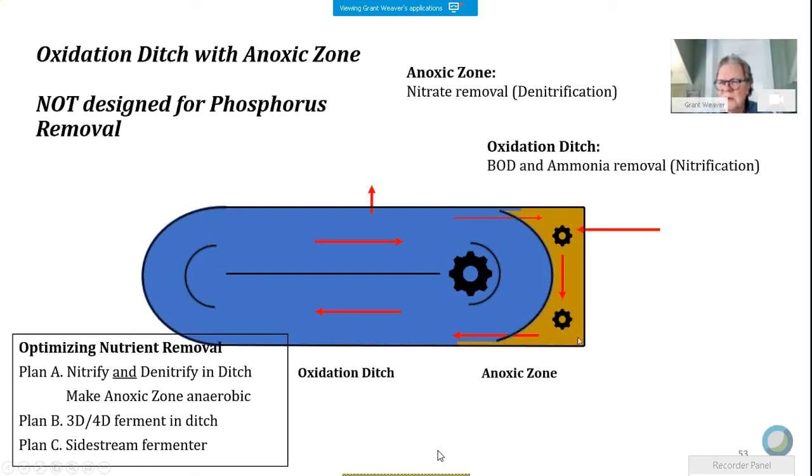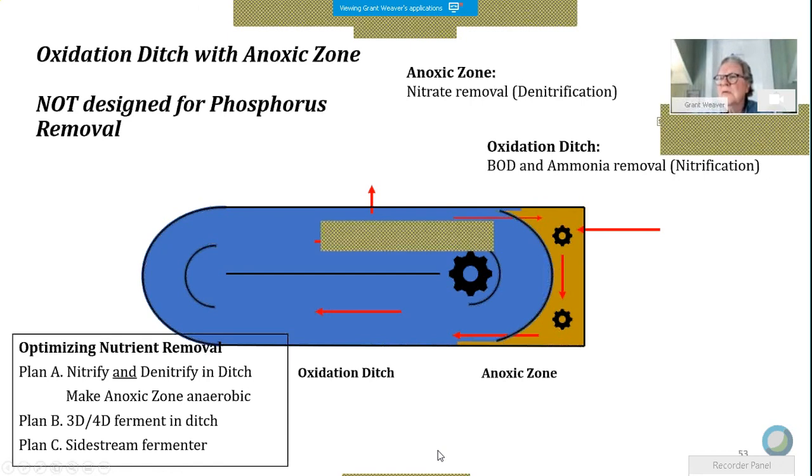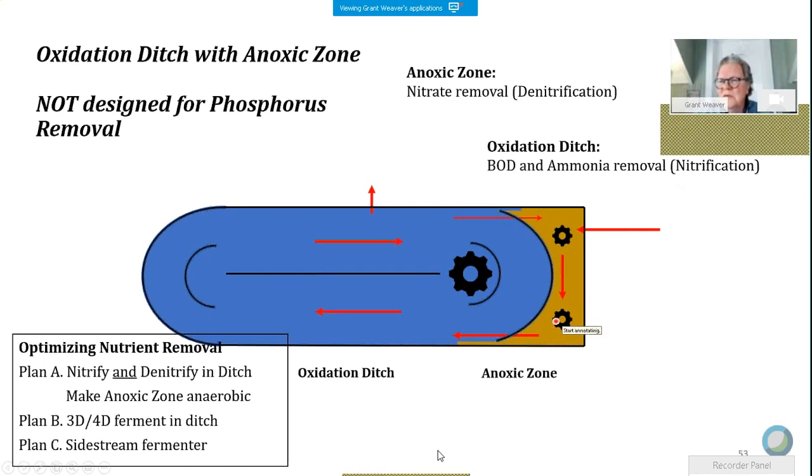So the ditch is still doing a good job. In the aerobic condition, the energized bacteria come in here, they suck phosphorus out, they go into the clarifier, and doggone it, in the clarifier they start releasing phosphorus. That will happen more likely in the warm weather.